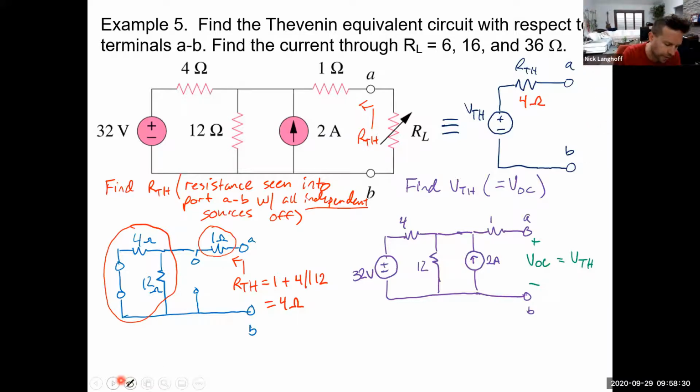All right, we'll draw the load back in there now. So here's RL. Now similarly, if the open circuit voltage VOC is shown there, then you know how much current is going through this 1 ohm resistor? By the same analogy, if it's open circuit, there's nowhere for current to flow through that 1 ohm resistor.